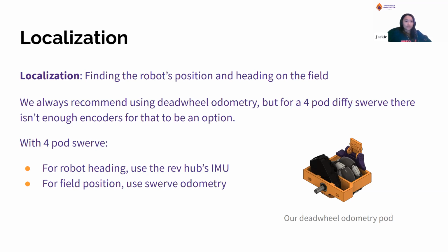One of the things we kept in mind was that if you want to design your own odometry pod, feel free to. There are lots of compact designs that have been remixed over and over again, so they've been refined over time. The one thing we do stress is spring-loaded odometry. Even if a field doesn't have any bumps, there are still imperfections, and there's more accuracy with spring-loaded dead wheel odometry.